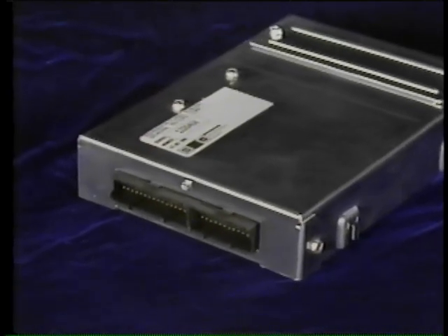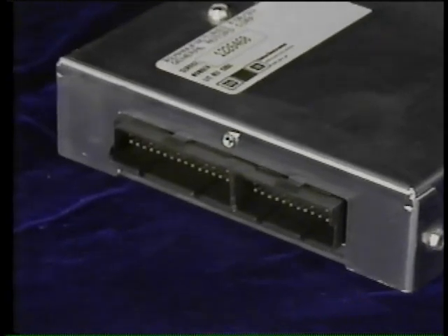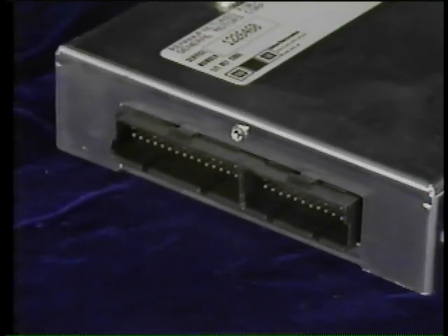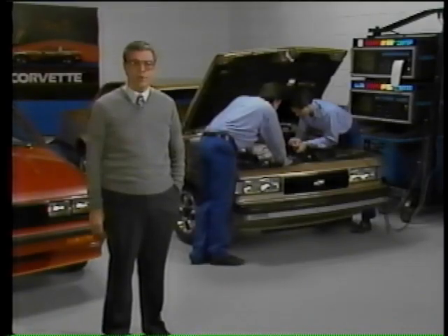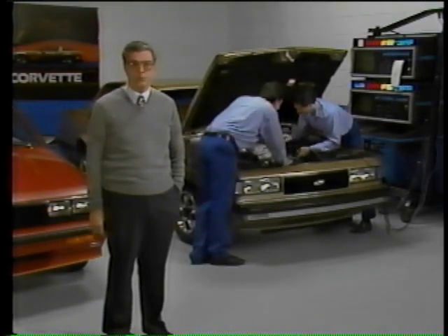In 1980, computer command control was introduced, and with it came the on-vehicle computer. Among other things, the computer had the capability of diagnosing trouble within the C3 system. This was made possible via the Assembly Line Diagnostic Link, or ALDL. The ALDL allowed the factory to run a complete check of the vehicle emission control system before it left the factory. Shortly thereafter, some electronics manufacturers thought service technicians could benefit from a tool like the type the factory used.